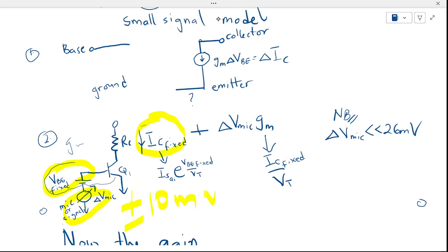And in this small signal model, we have the base of the transistor, and between the base and the emitter there is this junction here. So we can replace the junction with, let me change the color, a resistor.